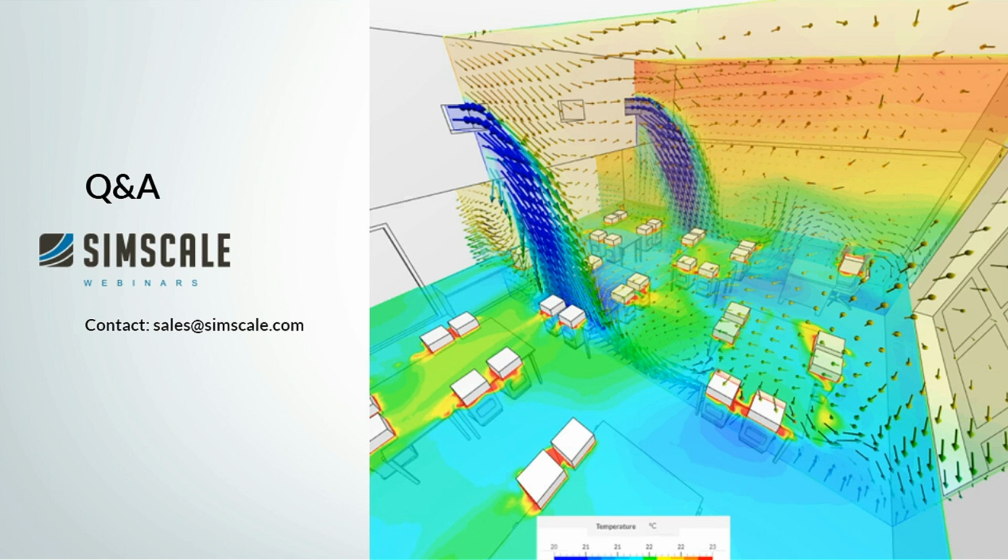So if there's a wall, it will assign layers to it. On faces which act as an inlet, there won't be a layer, but it will have a more refined mesh towards the inside of the domain, because we can expect some inflow in that direction. So in that sense, we already try to have a more or less optimized mesh as a default setting based on your physics.